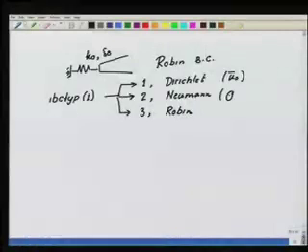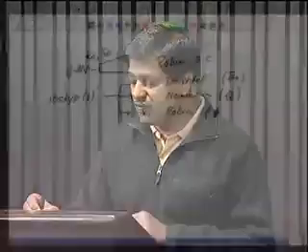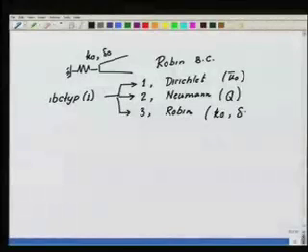If it is Neumann, I have to specify the end load Q, which is positive if it is tensile. And if it is Robin, then I have to specify the spring constant K0 and initial compression delta naught. These are the information that we need at this boundary.